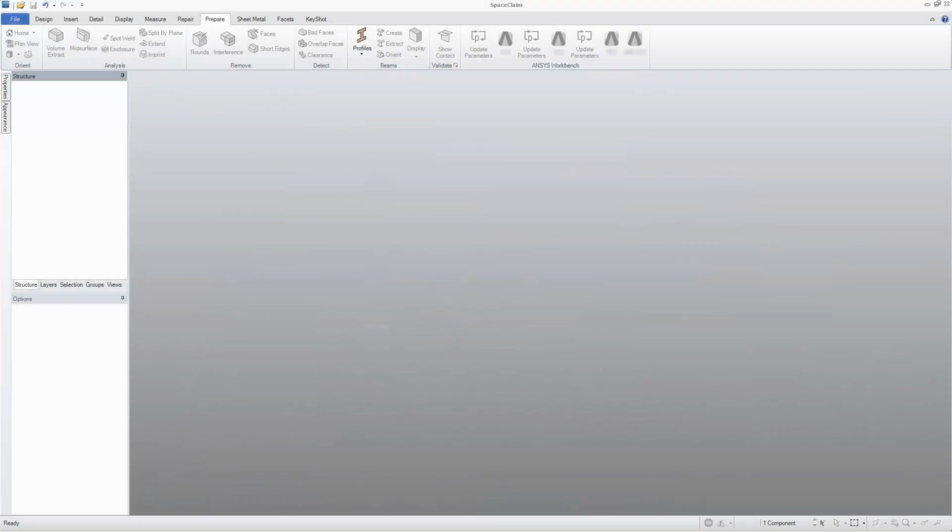In this video, you will learn how to perform mid-surfacing in SpaceClaim. Mid-surfacing takes solid parts and produces surface parts. This enables you to use shell elements instead of solid elements. Typically, there are far fewer nodes and elements for surface models than for solid models and solid elements. Thin solids are better solved as surface models. They solve more quickly and may be more accurate.